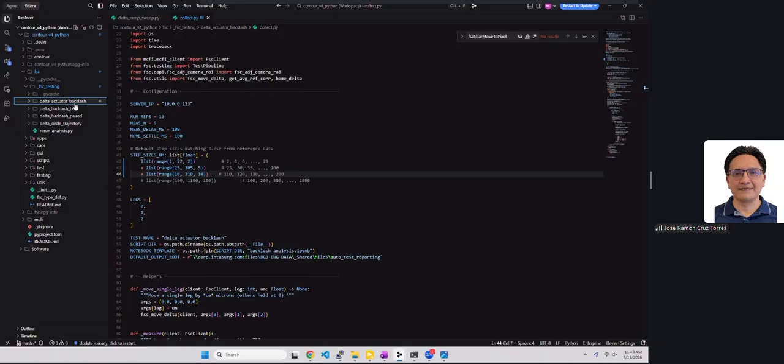But backlash is a much bigger issue because it affects the really tiny fine scale moves that we need to do for the thermal drift corrections and all the high speed corrections that we do for active alignment. It also affects the quality of the signal based optimization that you do here. So backlash is kind of the ultimate metric that we're mostly building towards.